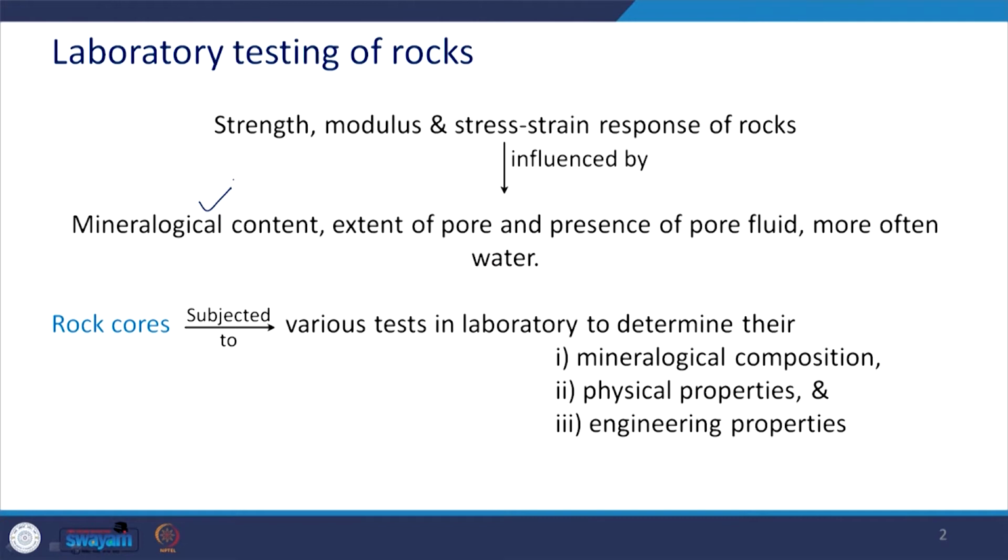Basically, the strength, modulus and stress-strain response of the rocks are significantly influenced by the mineralogical content of that rock, the extent of pore, and the presence of pore fluid in them, which is quite often water.